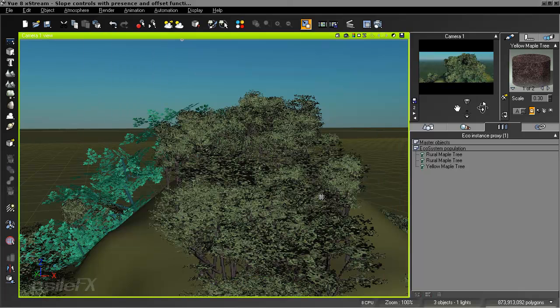So if you need to update the OpenGL to keep it the same, or so it looks the way it was actually going to look in the render, then you do need to use that proxy editing in the master object, or quote-unquote pseudo master object, in order to update that. Otherwise, if you want to keep them separated, that is kind of a cool way to manipulate the OpenGL without actually affecting the render.